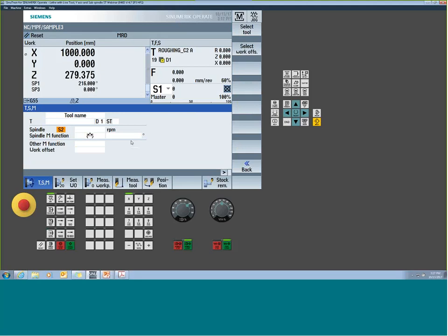But don't assume that if they're both at 0, 0, they're going to collide. There's no way to know. You've got to look at that specific machine to see where they all are. And certainly if somebody removes a chuck and puts it on, if there's no drive keys, potentially they could have it positioned another couple bolt hole patterns away, and then everything's going to change. So if you're swapping out your work holding, make sure you check that.